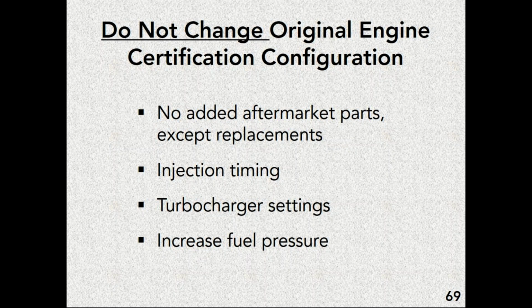You also don't want to mess with injection timing, turbocharger settings, or fuel pressure settings. These are all things that a good quality mechanic can do almost with their eyes closed, but they're also things that are going to change the way the system was designed. And ultimately, that's going to change the way the filtration system is capable of functioning.